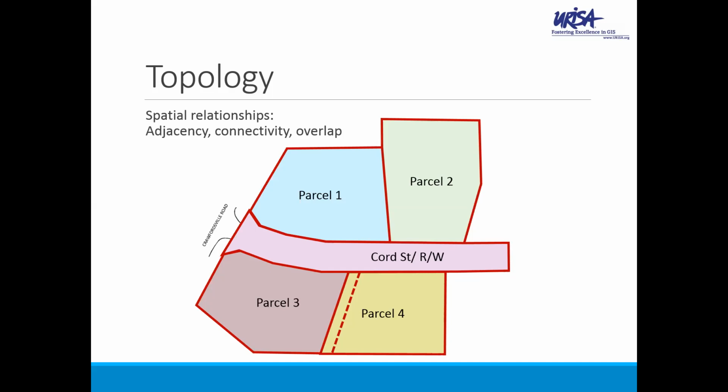For example, here, the total area of the entire 4 parcels is suspect, or the areas of the parcels individually, I should say, because of an apparent overlap between parcel 3 and parcel 4. The overlap may in fact exist on the ground, but either way, the system must know what to do with it if an area analysis is to be meaningful. Shall it be its own parcel? Or how do we show, in other words, the overlap? Maybe it should be its own parcel. How do we show that it's not merely a mapping error?